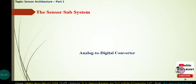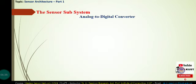Now, an important subsystem in that sensor is basically the analog to digital converter. A physical sensor contains a transducer, which is basically a device that converts energy from one form to another, basically to electrical energy. The output of this transducer is an analog signal, and that needs to be converted to a digital signal. So an analog to digital converter is required in this sensing subsystem, and that must have a digital processor.